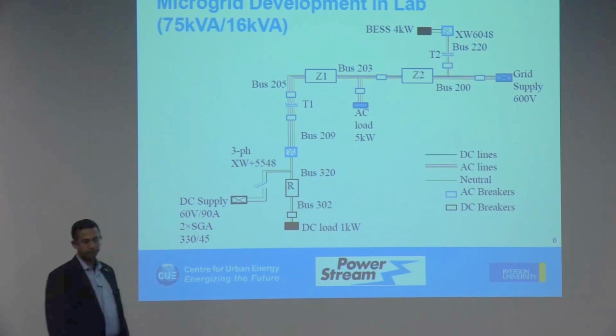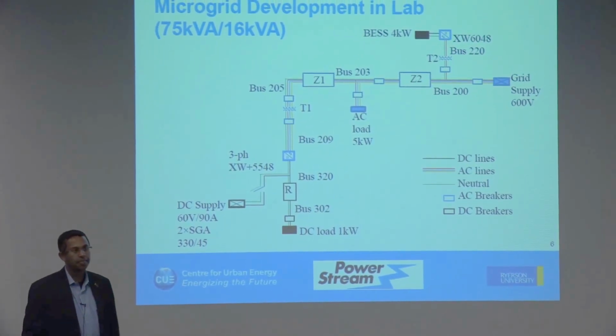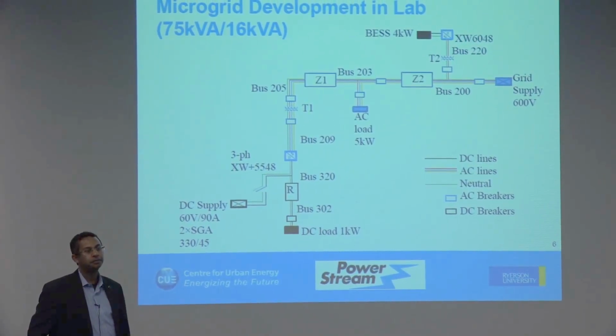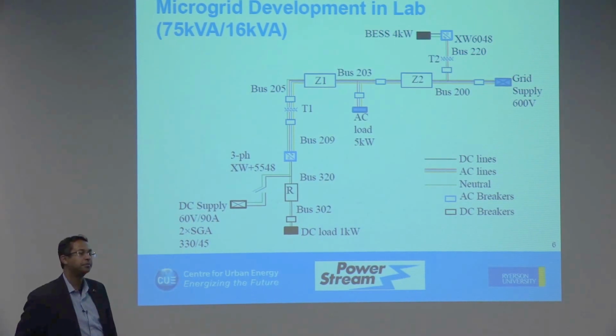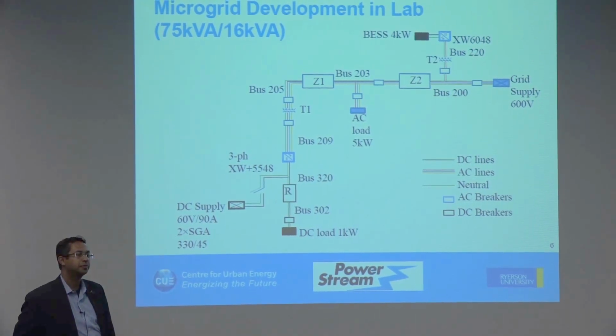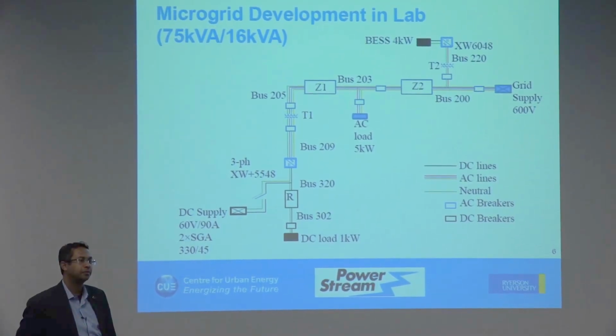Okay, can this bus be changed? Yeah, because if we have wind and a photovoltaic system, the photovoltaic output at night will be zero and the wind will be high at night, and that makes the slack bus change with time. Is this implemented in your lab or system?